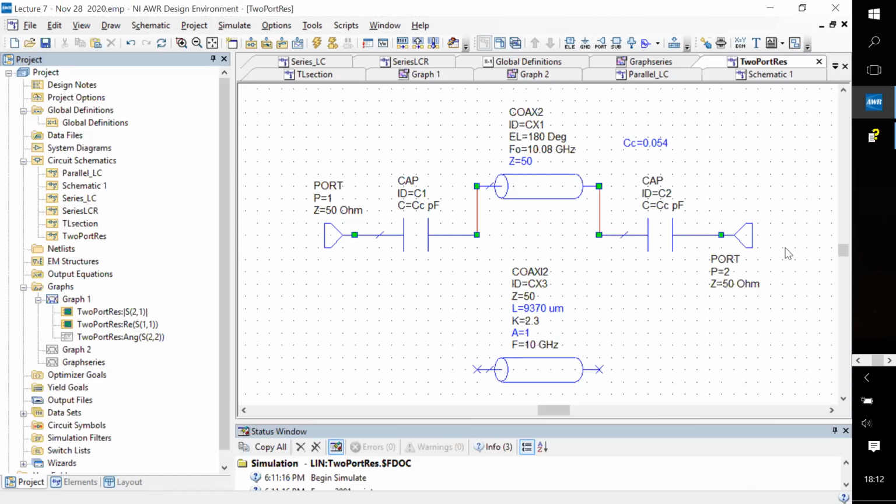It's not really the correct way to think about it. The transmission is perfect just means that when there's a wave incident from here, the multiple reflections which are happening here are allowing constructive interference to allow all the signal to go out of here. And there's destructive interference here, which is preventing any signal from leaking out of this side.